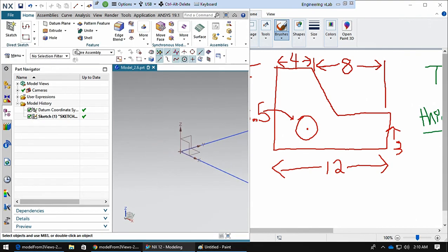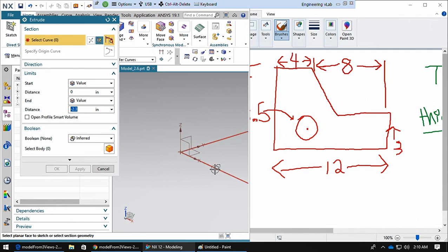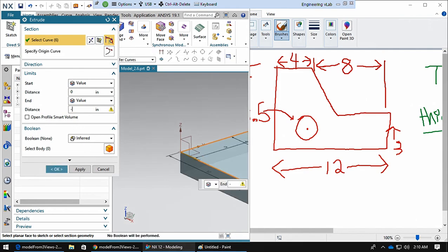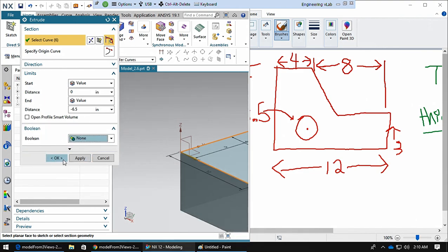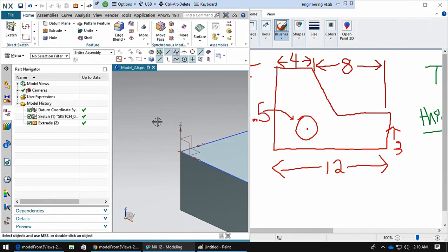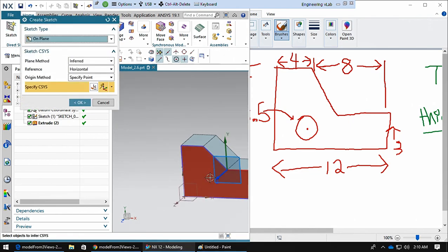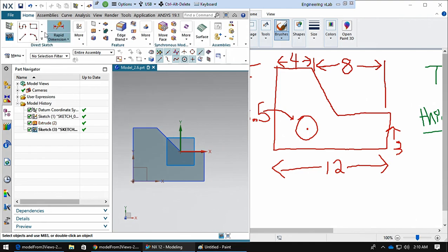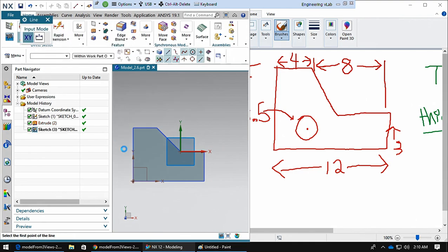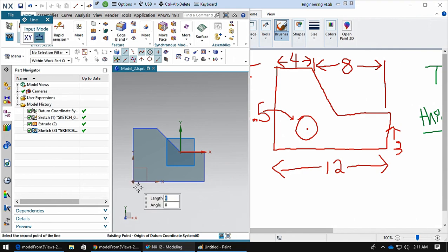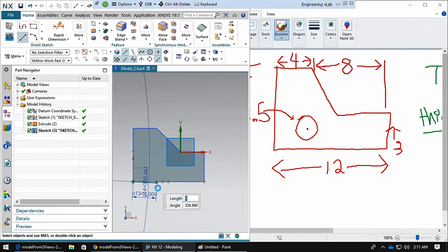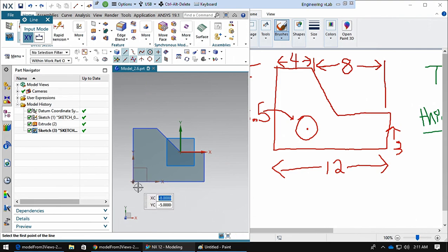Okay. Finish the sketch, we're going to extrude it. Again, same thickness, so minus 6.5. Boolean is going to be none. So we have that shape. We're going to sketch again. We want to sketch on the face. We're just here to make this hole. So we go over 4, press the wrong angle, Control-Z that.